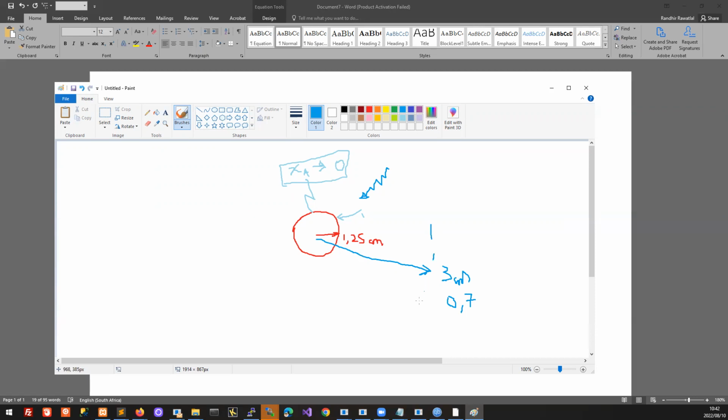So that means at any position around this particle at a distance of 3 centimeters, the mole fraction there is going to be 0.7. So we can see that there's a relatively high mole fraction or concentration of A out in the bulk here, and then A diffuses in towards the particle and the surface concentration is 0. Right, any questions or comments on any of that so far?